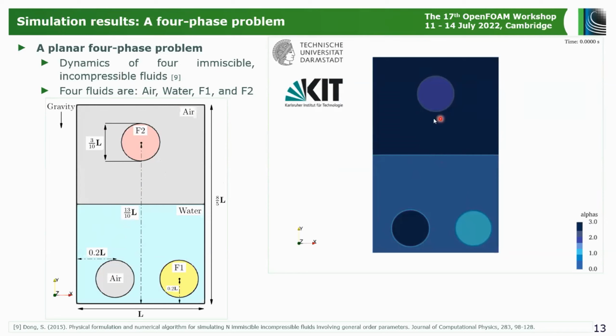The left and right are periodic boundary conditions, and when the simulation starts, due to buoyancy, the bubble rises. This F1 fluid rises slowly, and obviously the F2 fluid falls into the interface. We also have a small entrapment of air. Obviously, we have a 2D computational domain, so there is no way for the air to escape.